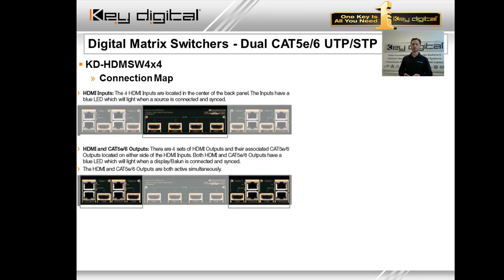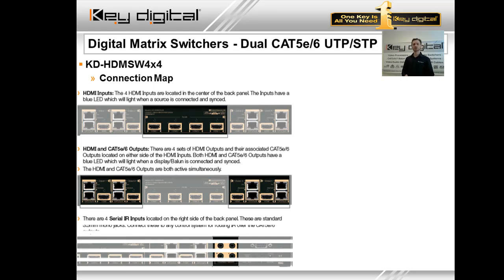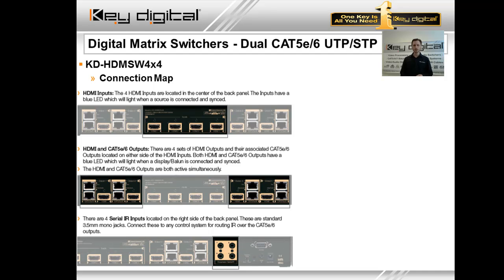You got an AV receiver right there in the equipment rack. You go to that with the HDMI. You got a projector or a flat panel on the wall. You go to that display with the receive balun, utilizing the display or projector for video, utilizing the AV receiver for audio. Now, Phantom series does not route RS-232, and it's not as sophisticated a method of control routing.